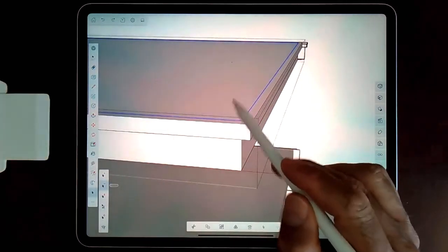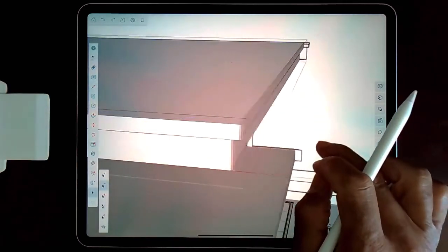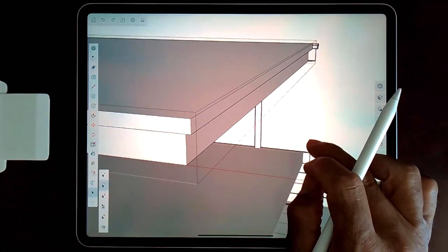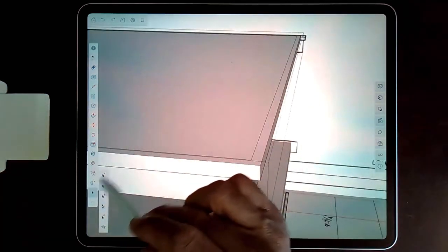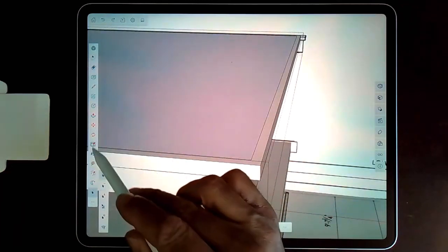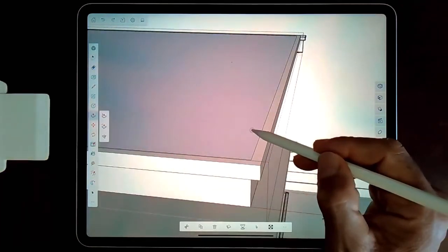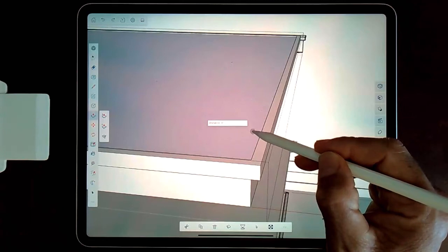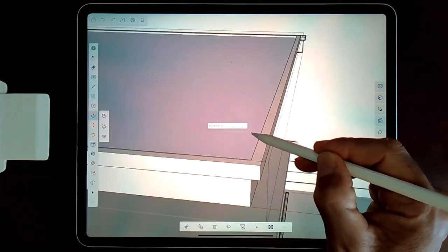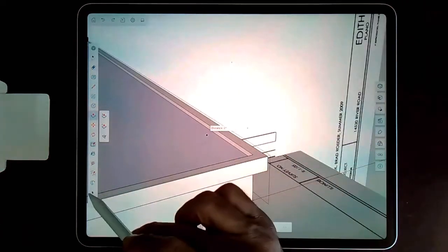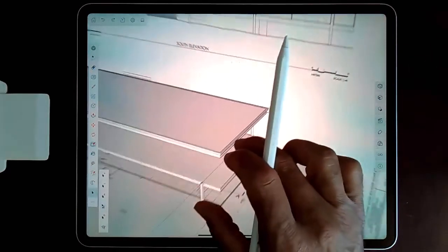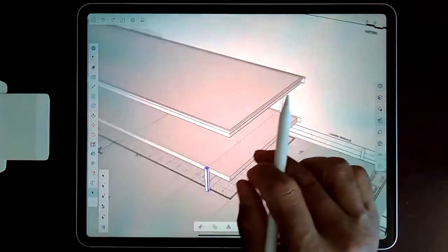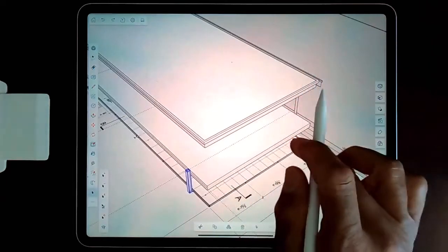So I was thinking about maybe taking this roof slab and maybe deleting it, but the more I thought about it, there is a slight sort of projection of this fascia. So why not just draw that as well? So undoing and going back, doing the double tap to undo and get that face back, and then pushing that down a couple of inches to get the detailing there of that roof line.